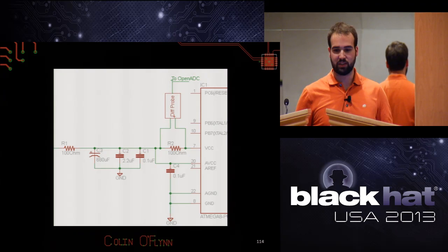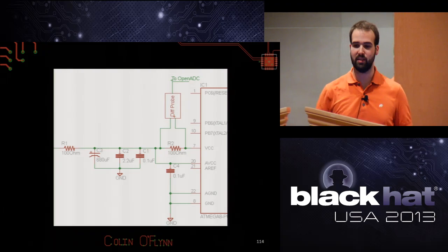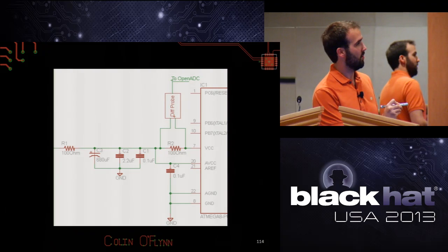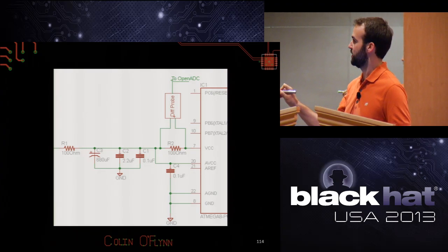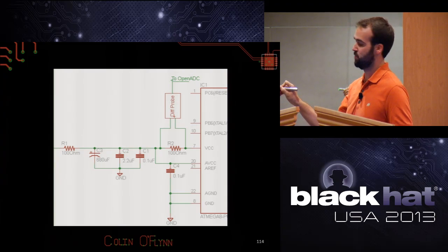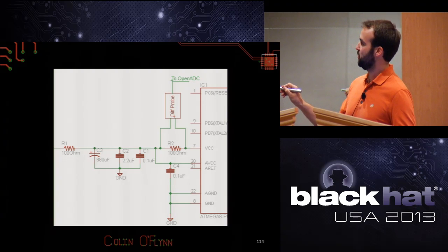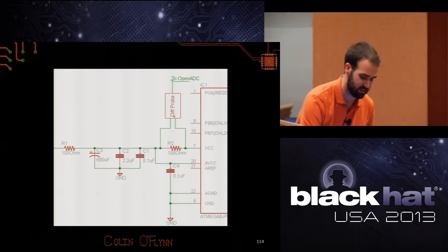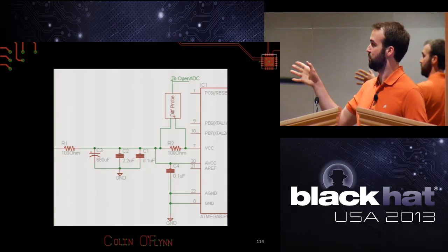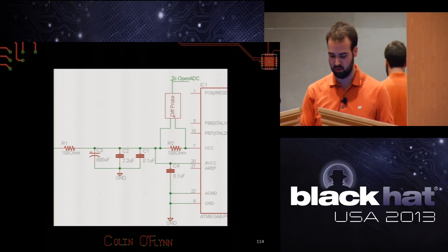So instead what we use is what's called a differential probe. All this does is you can see how there's a probe here and it's connected on each side of the resistor, that shunt I'm measuring with. The noise in the system tends to be coupled onto both sides of that resistor. So the noise coming through this line will more or less be coupled evenly to both sides. There's a tiny bit of variation, but we don't care. Now, this probe is only measuring the difference between the two sides of the resistor. So the noise that's common is irrelevant to the measurement. So this is a really easy way to sort of obliterate that noise problem.